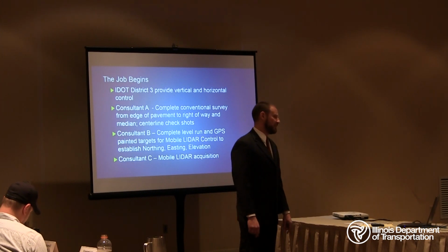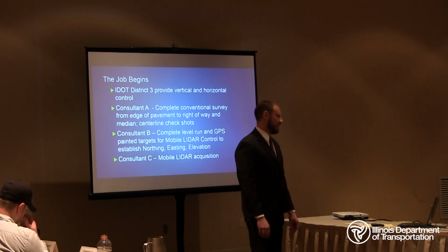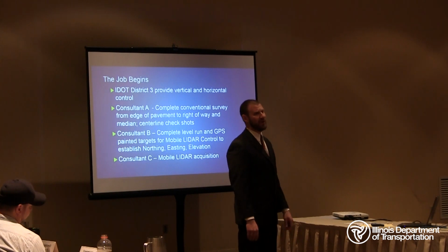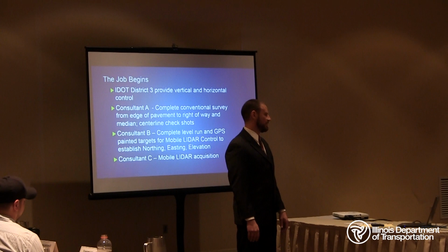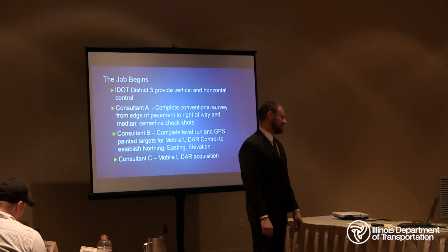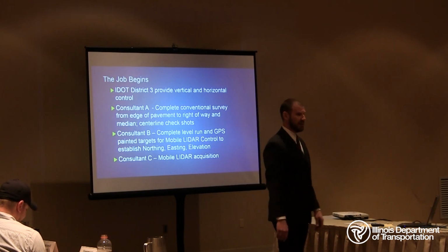Consultant B was going to complete the level run and establish northing, easting, and elevation on the chevrons, which are used to control the mobile LIDAR and get us those survey grade accuracies. And then Consultant C was going to do the mobile LIDAR acquisition.